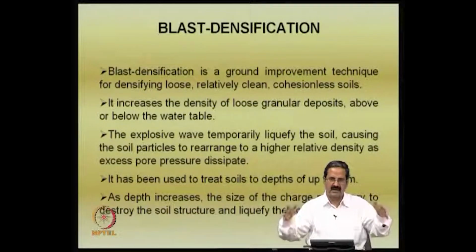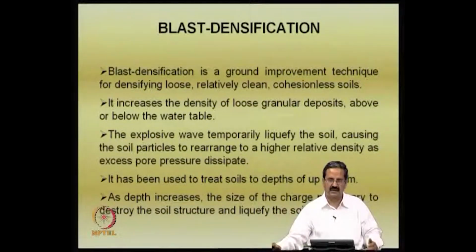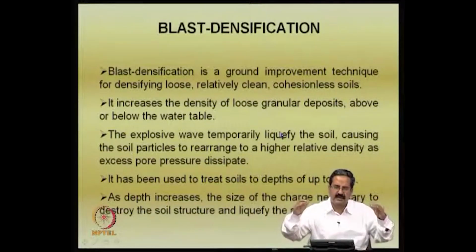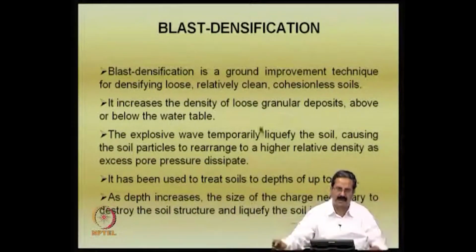So the consolidation is there in that sandy area. You are trying to accelerate it, to densify the whole area. That is the actual system here. You are essentially trying to densify. In this process, we try to temporarily liquefy the soil. We liquefy the soil a bit, and then there is a temporary development of pore pressures. This causes the particles to arrange to a higher relative density as excess pore pressures dissipate.